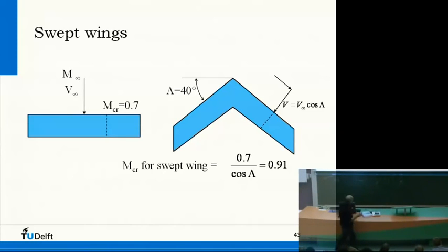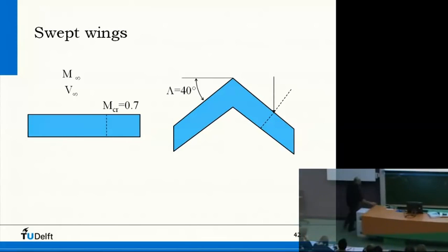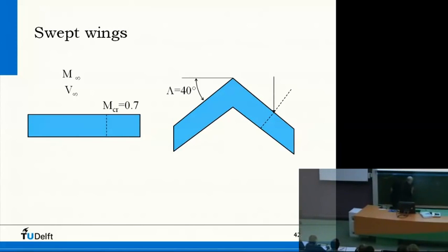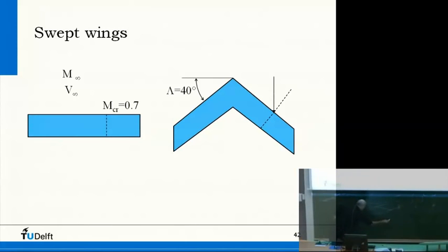What you could always also see is that if you have a thickness here, then if we go back a little bit and look in this direction, the airfoil will be thinner. If you cross an airfoil with this thickness, and you do not cross it perpendicular, but at an angle, like this, then it's in fact not this one, but it is this one.